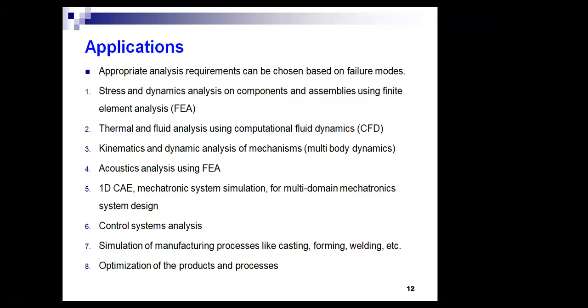A simulation of a manufacturing process actually involves a multi-physics environment. So it is not like a simple stress analysis of a product, a part or system. Manufacturing processes like welding involve a high level of nonlinearity in terms of geometry, material, and contact.